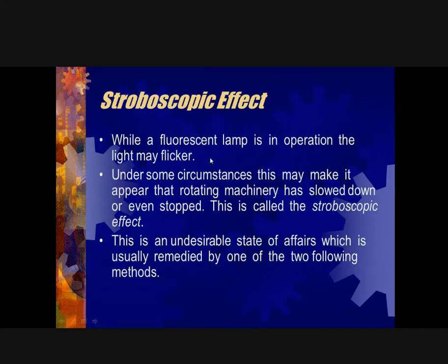To the naked eye, you will not see it, but under rotating or moving machines, it will seem that the motor is running slower than actual. You can see this in workshops. If you were to go to the mechanical workshop at UTech, you'll see this effect if you're under a fluorescent lamp. And there are ways to handle it. For our purposes in a machine shop, this is not a desired effect because we don't want the machine to look like it is off when it is actually turned on.